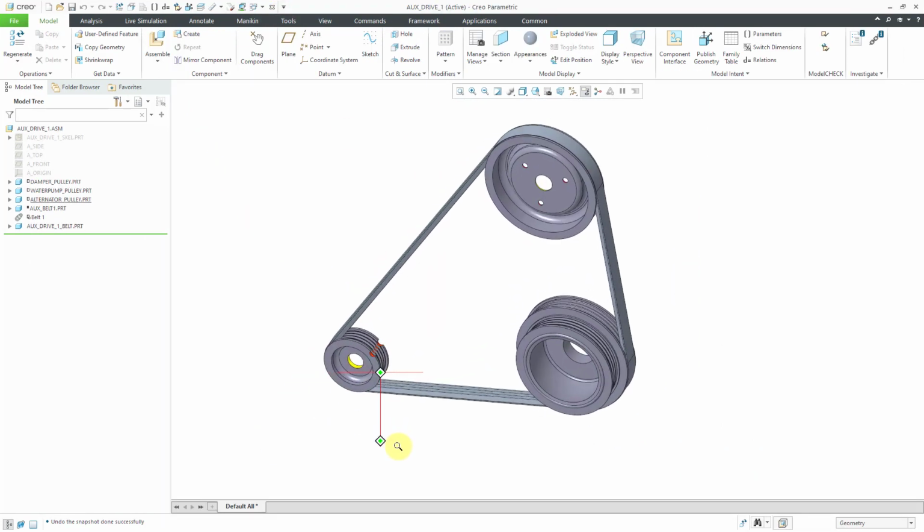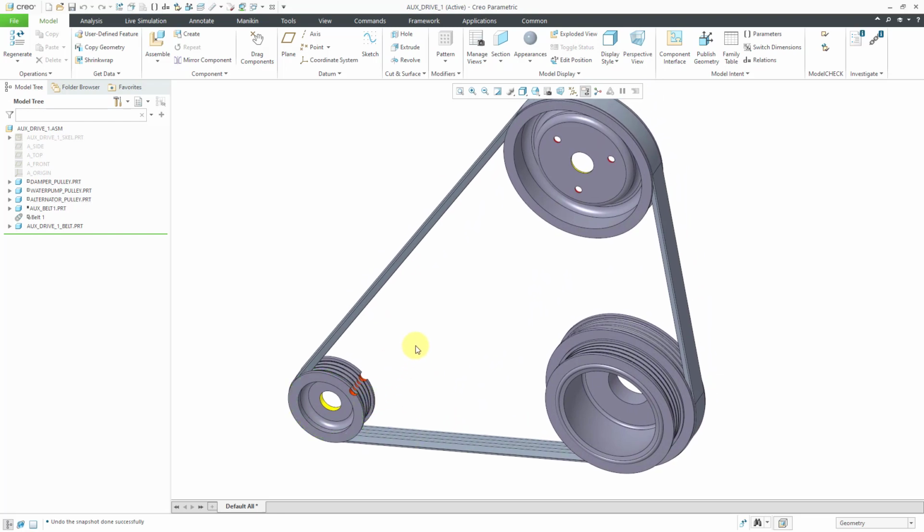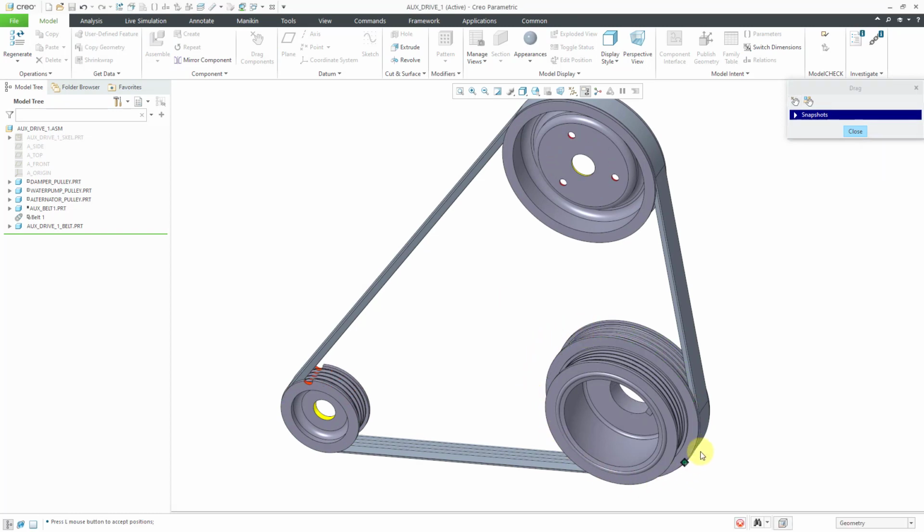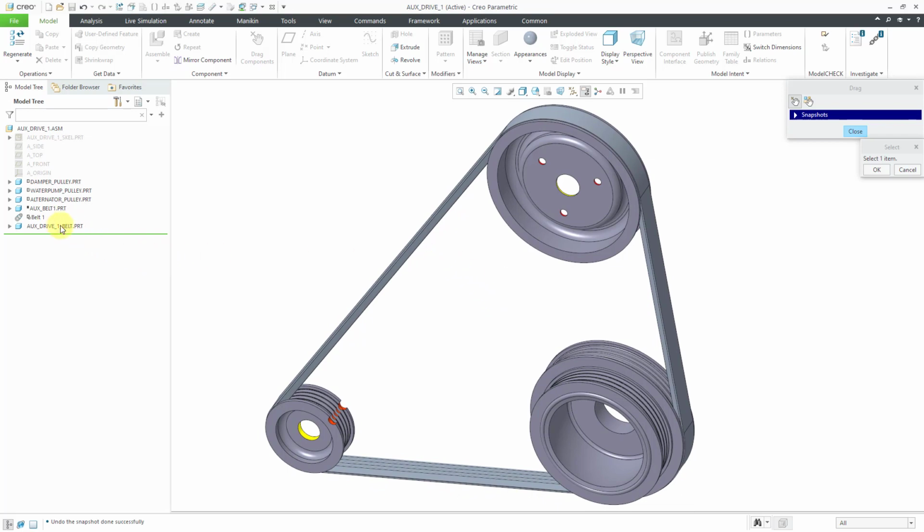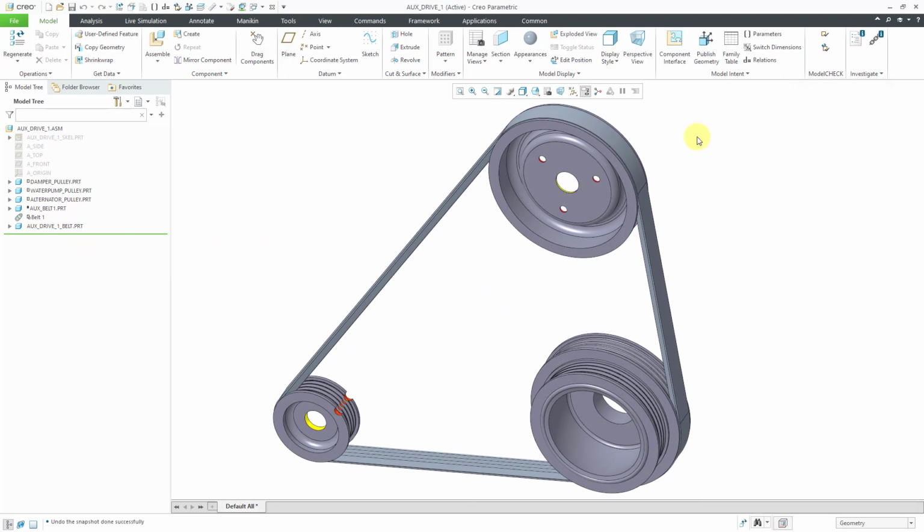And you can see where that cut is in that particular pulley. Now we can try dragging again. Click on the component. You can see that, yep, it is indeed rotating along with the other two components. It just doesn't have any natural geometry that allows us to distinguish that actual motion is going on in this case. So in that way, I have created an actual mechanism connection inside of my assembly. I no longer need this belt, so now we can actually delete it. And that's how you can use belts in a mechanism.